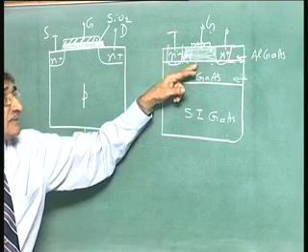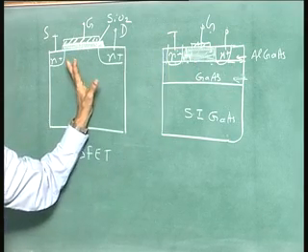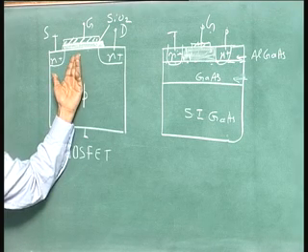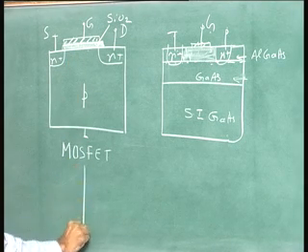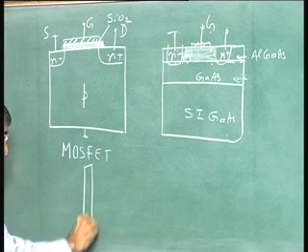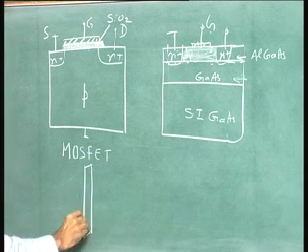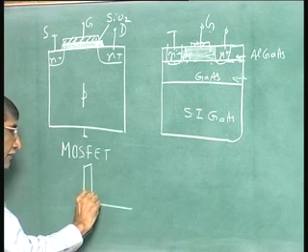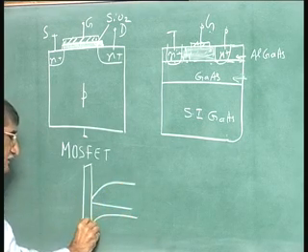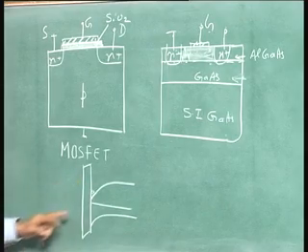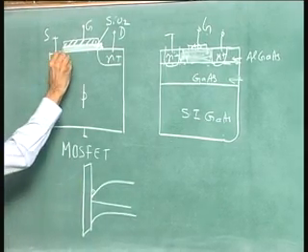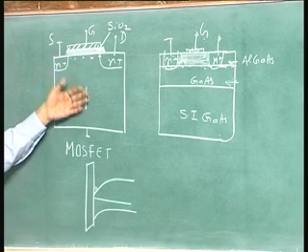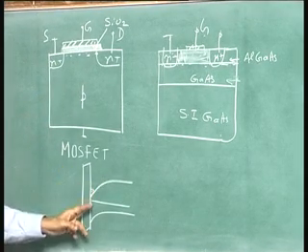The added thing here is that this is almost equivalent of this, or exactly equivalent of that. You have got the notch here, which I have discussed earlier. Recall the p-channel: that is the oxide, and then you have got the Fermi level, and the band bending taking place like that. That is where the electrons are held up, the electrons here, the inversion layer. Threshold voltage is the voltage at which the band bending is such that it becomes completely n type.